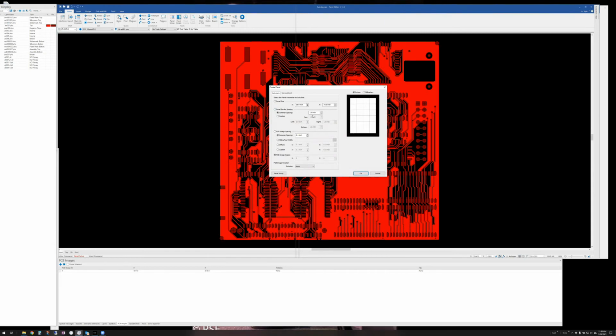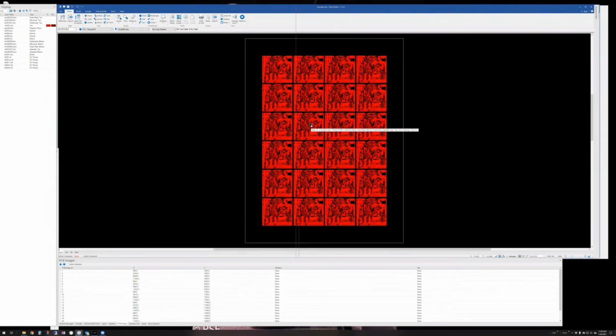It's a pretty square board. Maybe I don't need 1 inch all the way around it. You know, I can put a 1/2 inch and see if that does anything for me. It doesn't look like it does much. And then when I'm done with that, oh, I should show you there is a spreadsheet mode where you could put boards in here, you know, and move them individually if you want to. But for right now, I could have it recalculate the panel size, but generally that's not what fabricators do. Fabricators have set panel sizes, and they're going to fit the boards on that set panel size. So 18 by 24 in this case, I hit OK, and it goes ahead and steps the data.